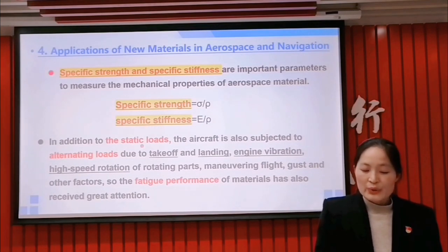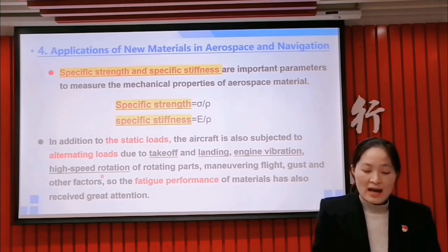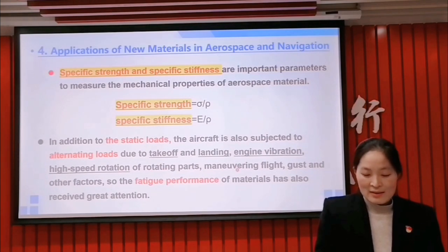In addition to the static load, the aircraft is also subject to alternating load due to takeoff and landing, engine vibration, high speed rotation of the rotating parts, maneuvering flights, so the fatigue performance of materials has also received great attention.